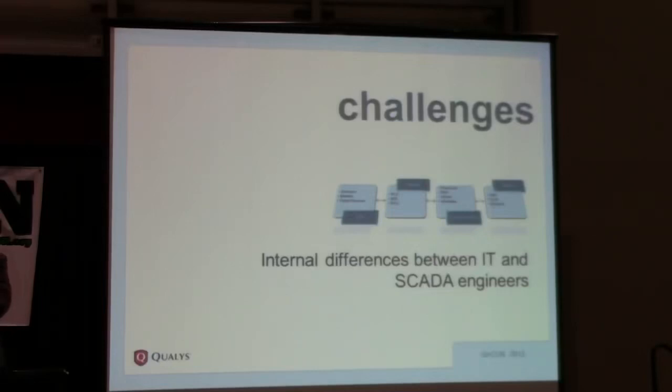And then the SCADA team says, okay, you guys are never going to scan or do any audits on my system. And that happens often. So if you are on the team which tries to secure the system, please talk with your SCADA people first and try to get a window where it's okay if something goes down, because more or less when you scan a SCADA system, something will go down.